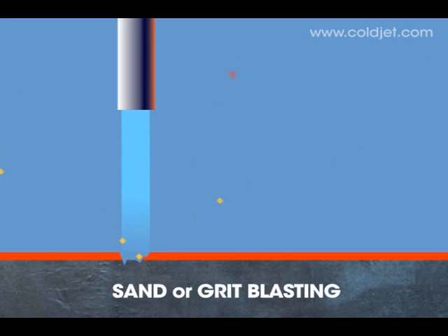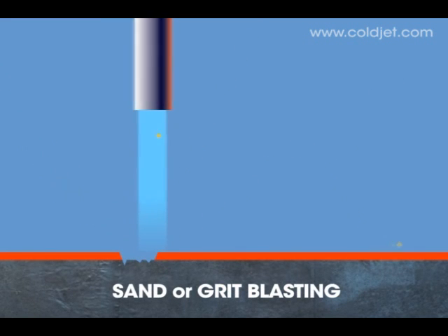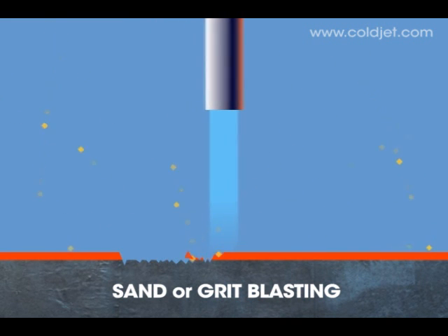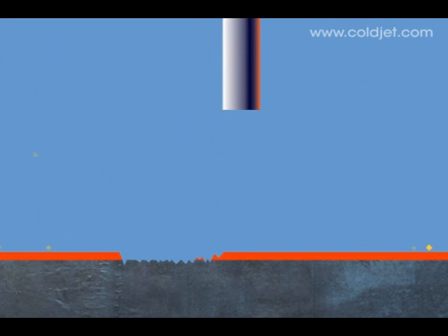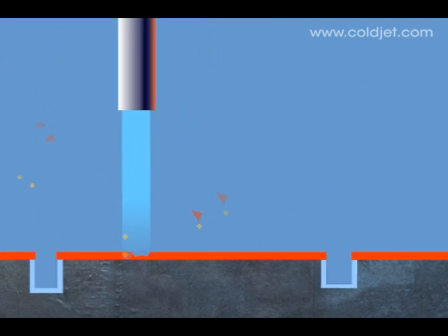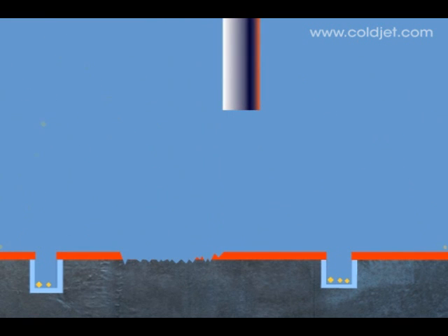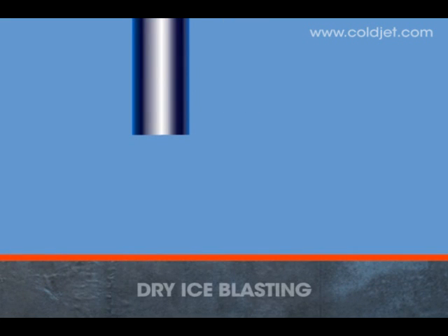Although it effectively removes surface contaminants, it also picks away at the substrate, wearing it away over time, altering surface geometries, destroying critical tolerances. Sand particles can also become entrapped, causing critical problems that can shut down the manufacturing process while the problem is solved. Dry ice, on the other hand, disappears as it cleans and will not alter most industrial substrates.